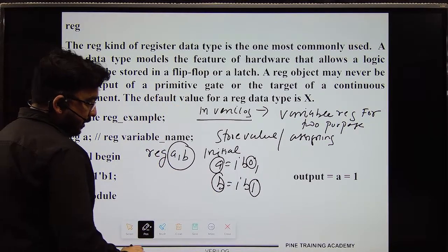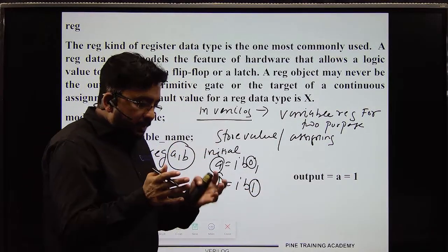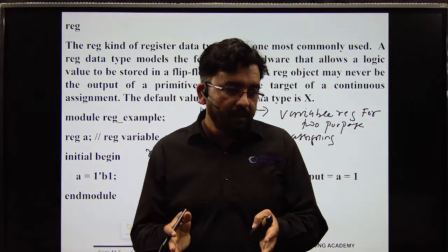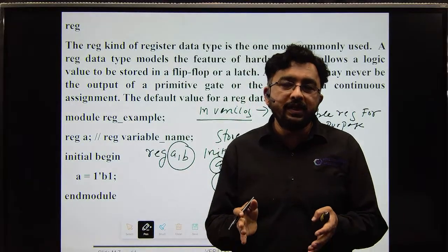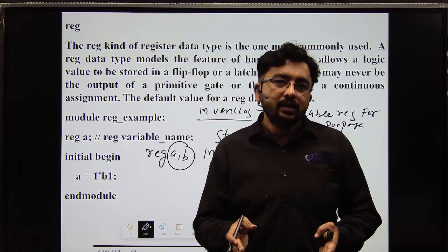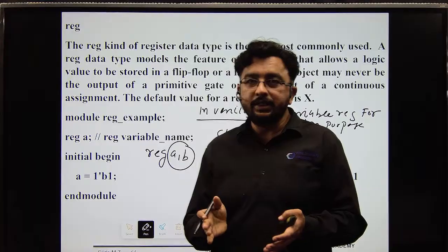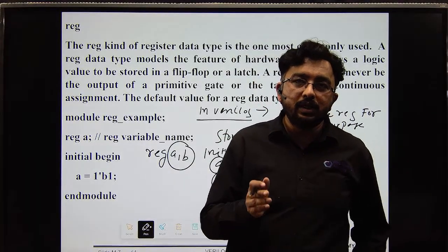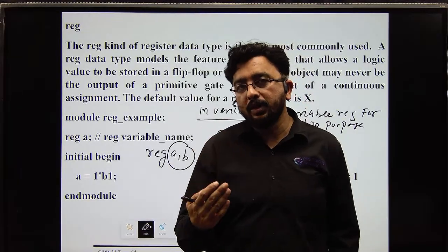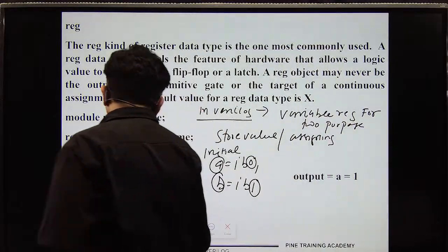And second, whenever you are making logic which represents some hardware, for example D flip-flop, T flip-flop, JK flip-flop, counter, shift registers, any type of sequential logic, then the sequential outputs you also have to declare with the keyword reg.